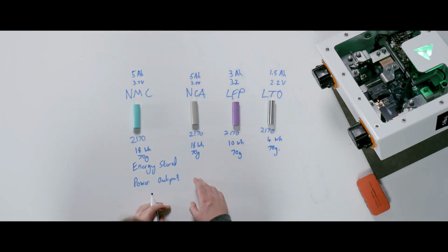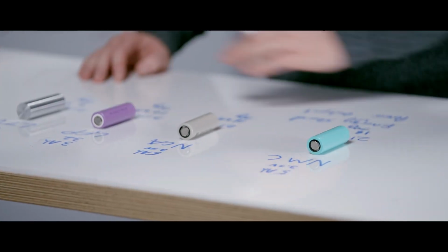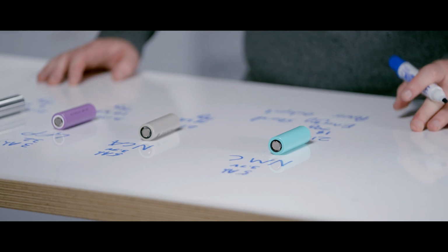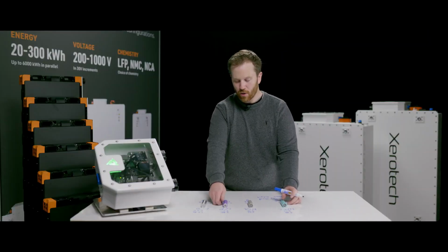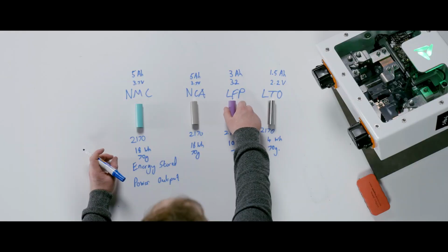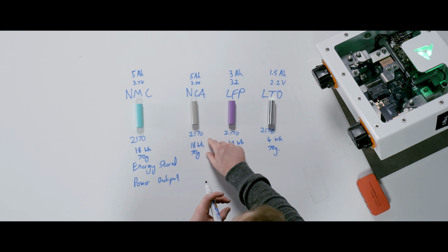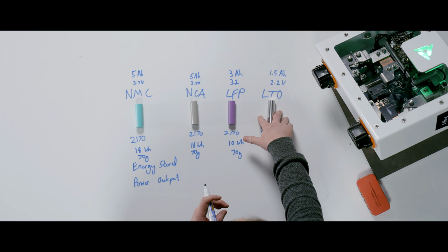So the big difference here is, as you look at the different chemistries, this is what it's actually like on today's market with cells you can really buy today in cylindrical format. For these same two cells, 18 watt hours. By going to LFP, you're down to only 10 watt hours. So it's a significant amount of energy reduction in the LFP. And the LTO is dramatically smaller again.